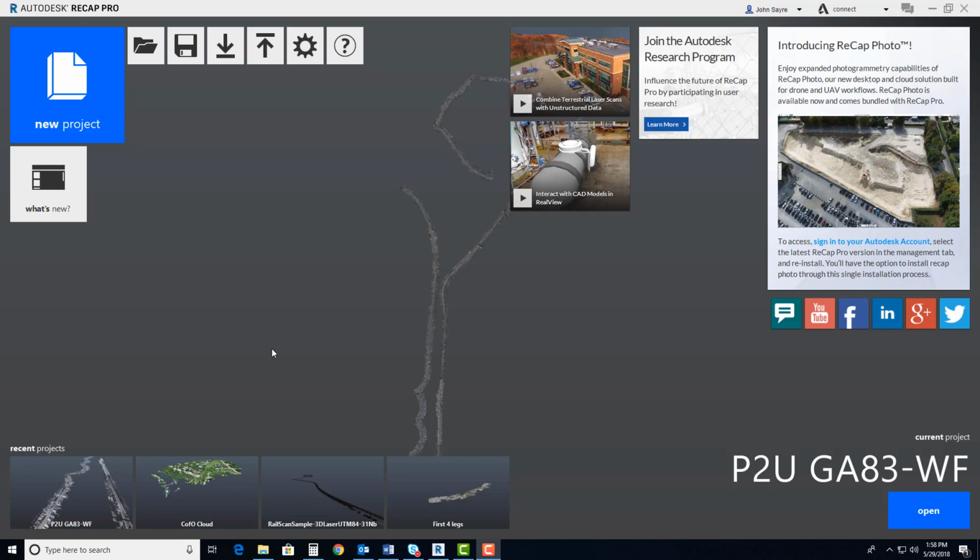Today I would like to walk you through one part of the scan to BIM workflow. We will begin with Lidar to design. This process will start off with raw scans from the field that we bring into Autodesk Recap Pro. Then we will take the processed point cloud into Infraworks and create a surface so that we can run linear feature extraction. From there, we will bring the linear features and the surface from Infraworks into Civil 3D so that it can be used for design.